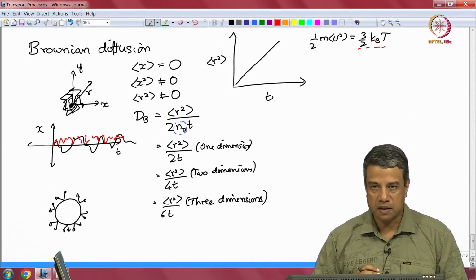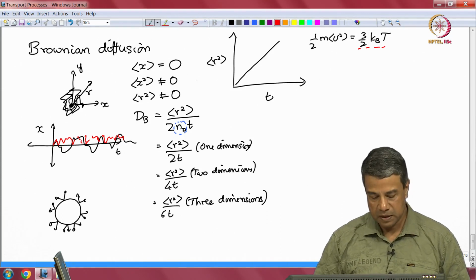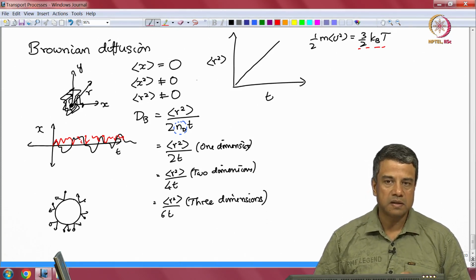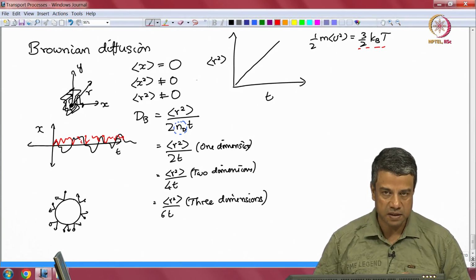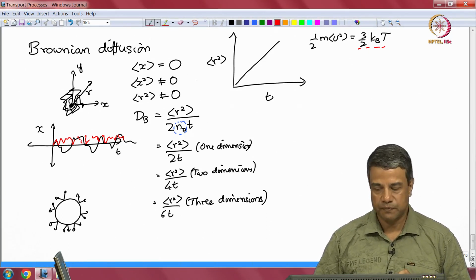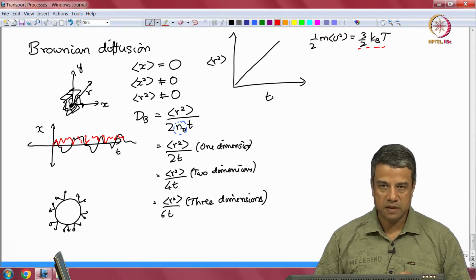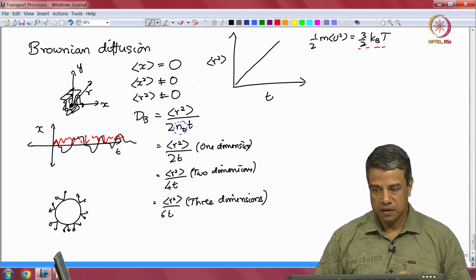Recall that when we did the particle settling in a fluid, I said that at low Reynolds number the force is entirely viscous. These are very small particles of the order of microns in size, and therefore, you would expect the force to be entirely viscous. Therefore, the fluid density will not affect the drag force, it is only the viscosity that will affect the drag force. So, therefore,